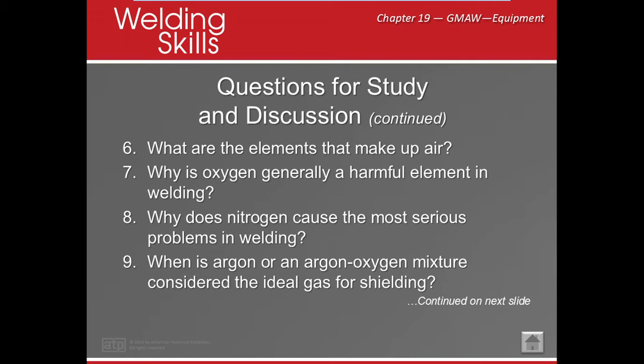So oxygen is really reactive and it combines with other elements in our weld, okay? And it forms oxides and gases. And if the deoxidizers didn't take the oxygen out, it combines with our metal and it can cause porosity. And ultimately that porosity, those little holes that are coming out, are actually the gases coming out before the material solidifies. Okay.